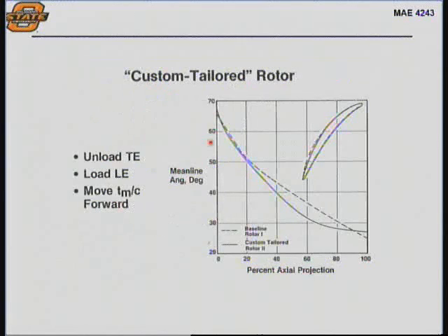for these calculations. So some of the things that designers do to get that last 3 or 4% of efficiency are to custom tailor designs. As I said early on, compressor airfoil design was very, very simple. They literally used circular arcs for the upper and lower surfaces and made blades that look like that.